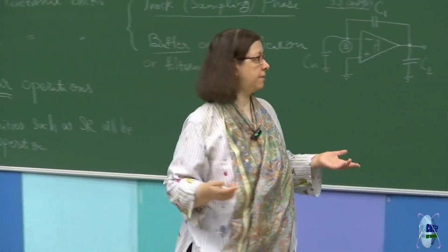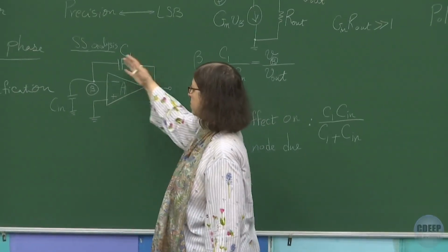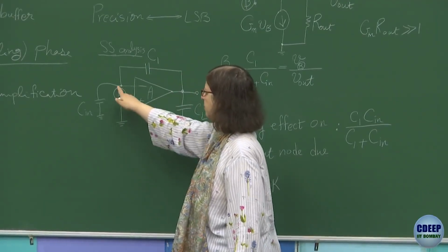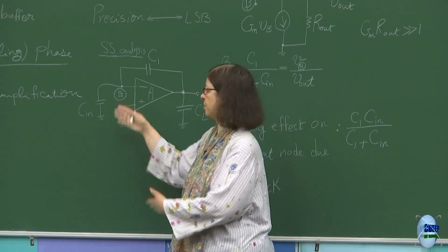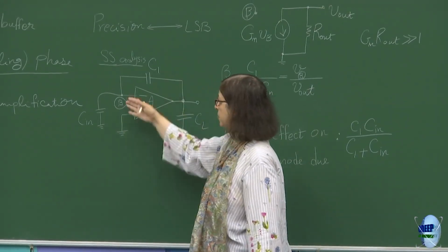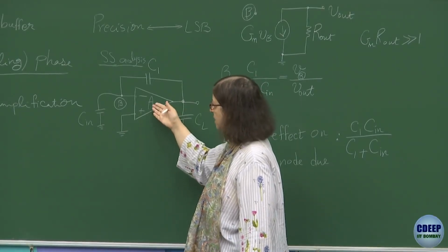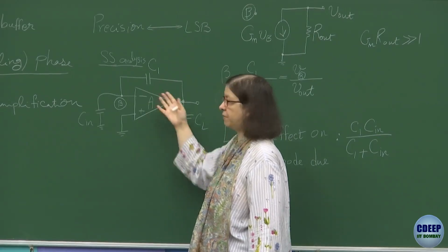In an ideal feedback, a feedback is also a kind of two-port system, and you can have only one factor, like input voltage as a function of output voltage, like a voltage-controlled voltage source. But when you create a loading, this loading has an impact on what this module A could have generated if the feedback had not been there.